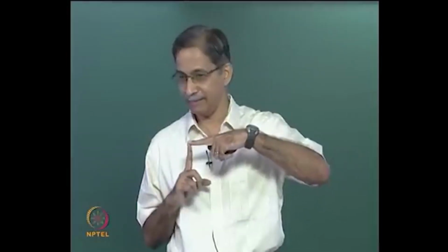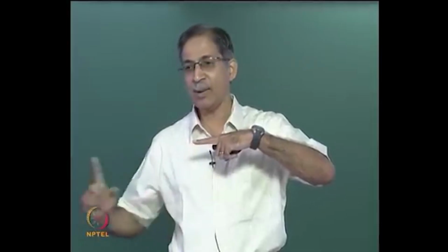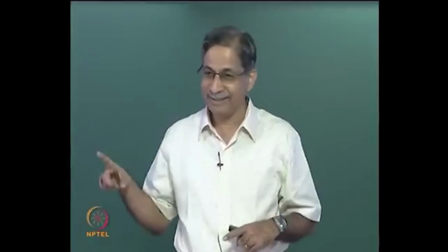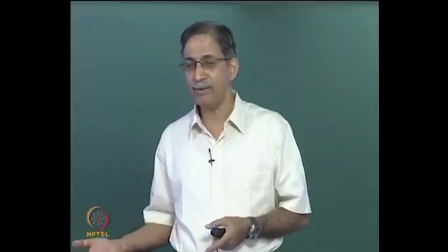Let that be very clear, right? So you can quietly remove the child from the picture and look at the parent. Parent is a cantilever. Now if you apply a moment at joint B in that L-shaped cantilever, do you think anything will go on to elements 2 and 3? No. So this is the flexibility method. You really have to enjoy the physics of the problem and get the answer. So you just have to draw this.